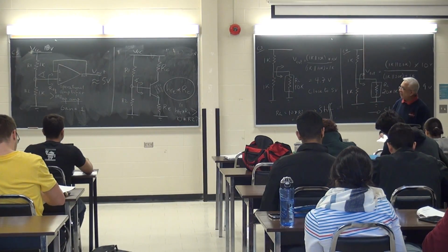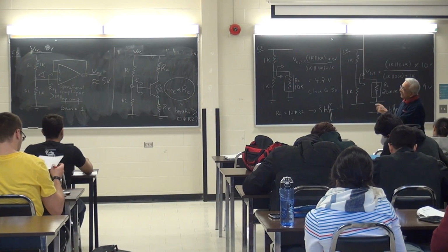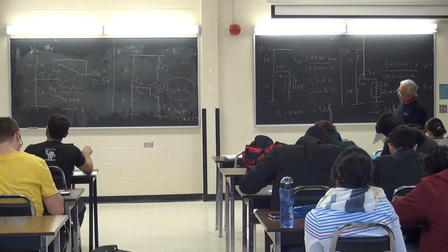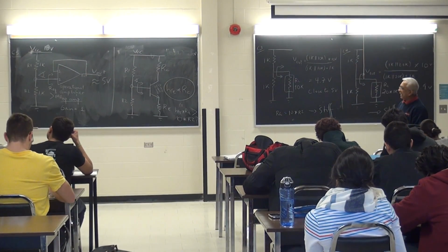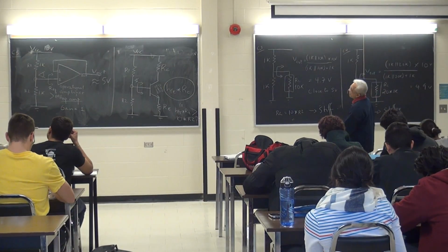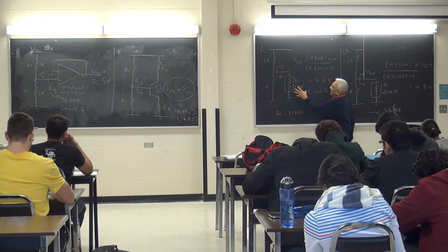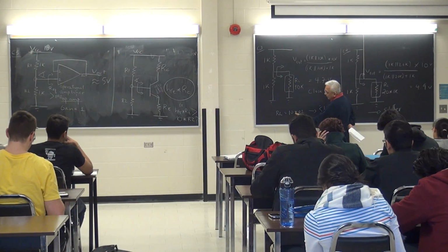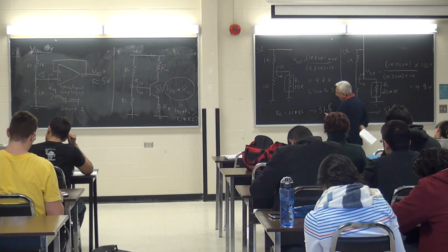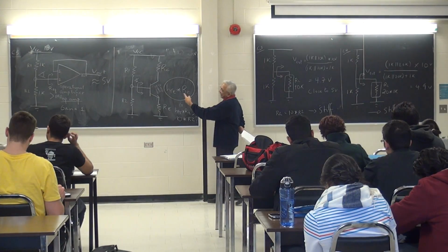What is the criteria? You're going to test your circuit for stiffness by asking, is HFE times RE greater than 10 times R2? This is the R2 value. Remember, back on page 13, when I was analyzing this circuit, I said RL is 10 times R2. So this concept of 10 times R2 for stiffness applies to the transistor circuit as well.